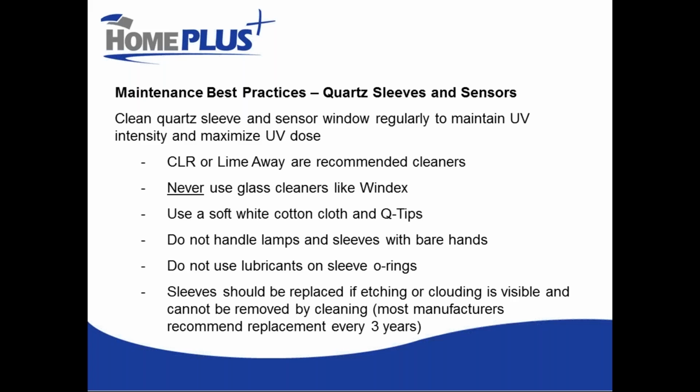The little sensor windows need to be cleaned as well. They have a quartz glass window, and you just unscrew the sensor from the side of the chamber, use a Q-tip with some CLR on it, or you can even get a little thimble or a tiny cup and soak the end of the sensor window in the CLR for up to half an hour to break up stubborn deposits if they're there. Rinse both the sleeve and the sensor window off with nice clean water before putting it back into service.